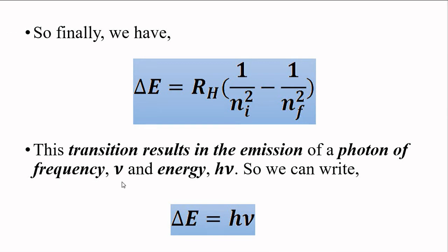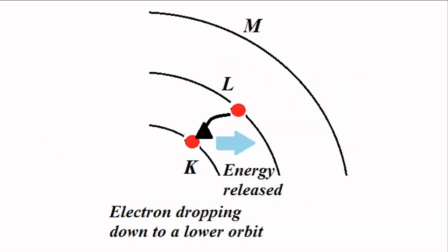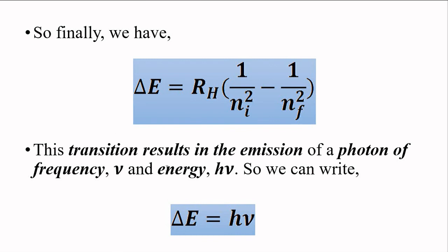This transition of electrons from one orbit to another, on the basis of emission and absorption of light photons of particular frequency and energy, forms the basic principle of operation of optoelectronic sources and detectors. This frequency will determine in what wavelength range or frequency range we can use a particular optoelectronic source or detector, in which region of the electromagnetic spectrum.